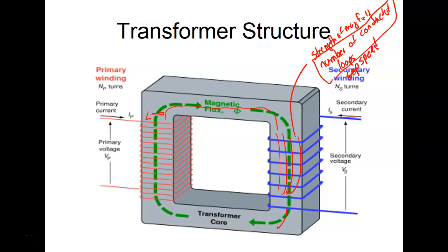So this transformer here, we'll look at in a minute. We can wire this transformer either to divide by 4 or divide by 2. And this is very popular in industry because industry usually has at least 2 different voltage levels out there. One of the most popular voltage levels in industry is 440. So what would be the advantage of 440 over 220?